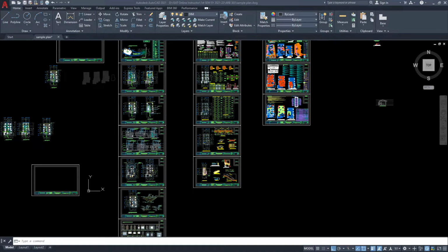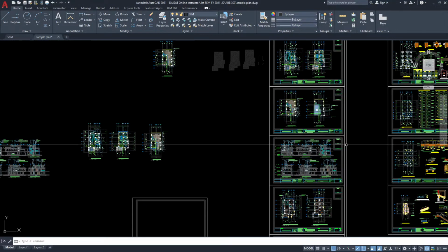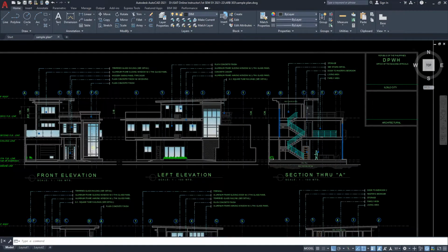So cross-section, also simply called a section, represents a vertical plane cut through the object. So the same way as floor plan is a horizontal section viewed from top. So in the section view, everything cut by the section plane is shown as a bold line. It's often with a solid fill to show objects that are cut through and anything seen beyond generally shown in thinner line. So pakita natin ang section through.